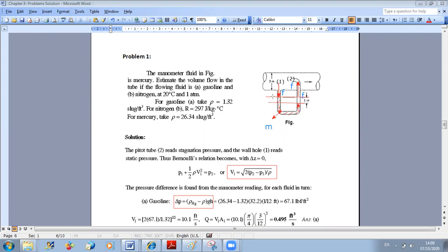So you say, when I move from this point to this one, what is happening? The pressure is increasing. So we will write that P1 plus, you are moving in which fluid? In mercury. So plus gamma of mercury times distance h equals, now here you can do the jump, because you are going down and up in the same fluid. Since I'm going down and up in the same fluid, I can directly jump to this point. Once you jump to this point, you will go up now to reach this level. You will go up in which fluid? In F.